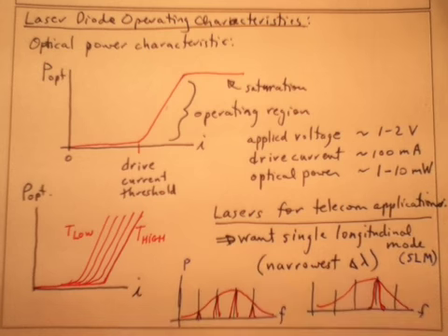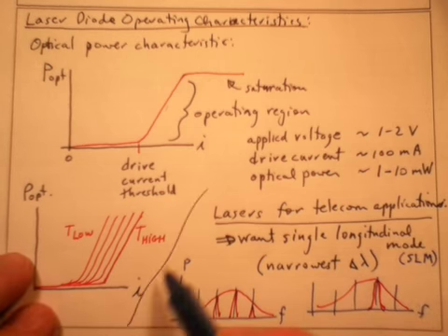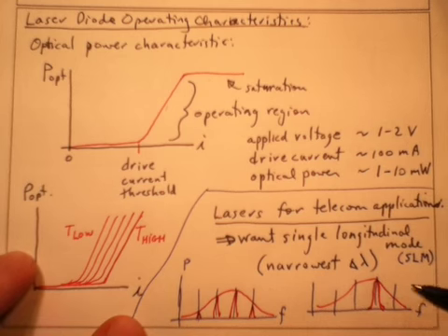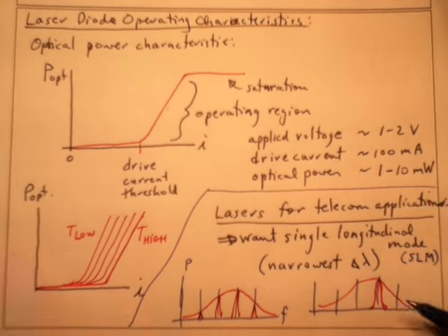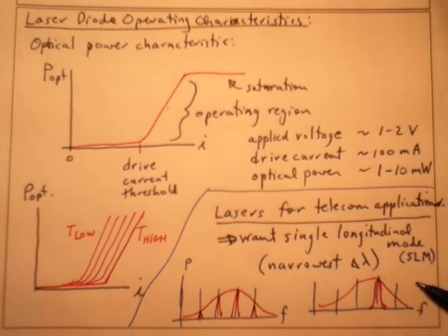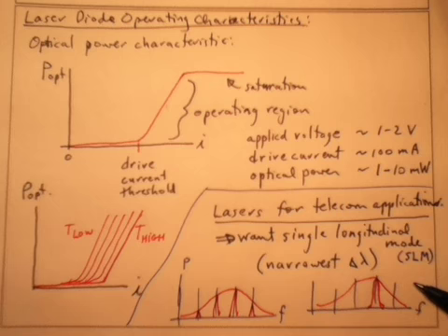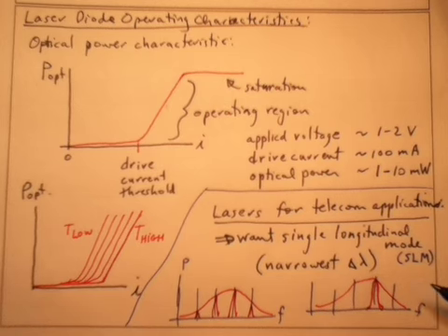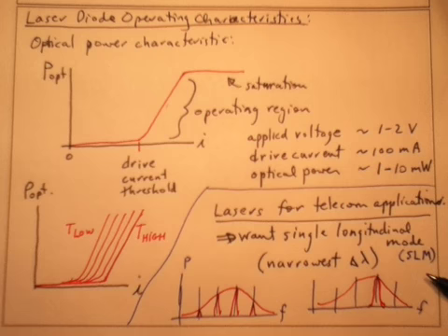And they're much more preferred. We're always trying to get a single mode laser out of our structures to give us the highest bandwidth, and generally speaking, that is the type of laser that we'll use in our telecom systems. We can also make them tunable through various tricks, and that's nice for WDM systems. We won't get into any of the details on how all of that works here, but we can make tunable laser diodes. Okay, I'll stop here. Thanks.